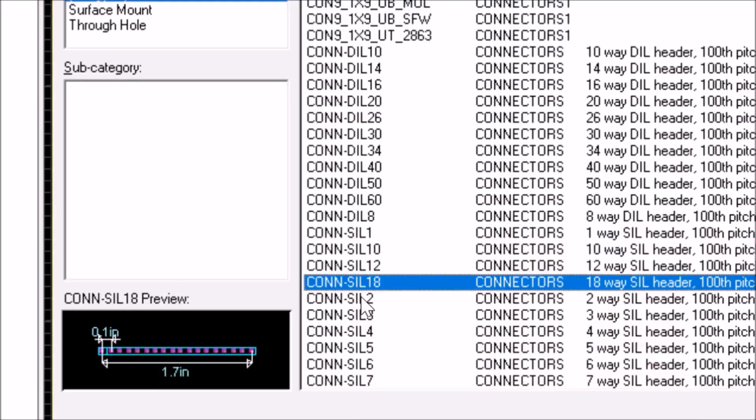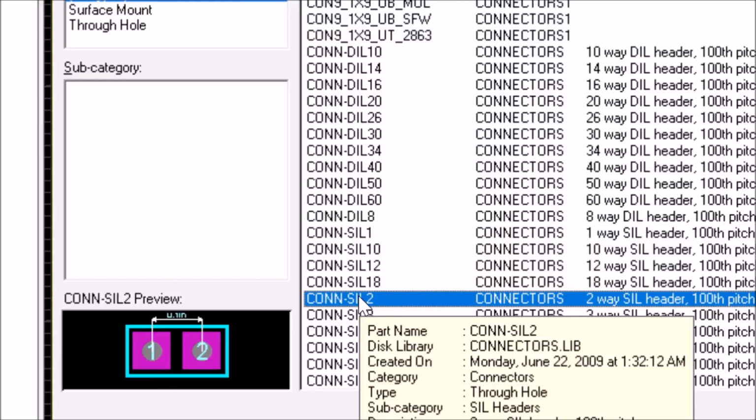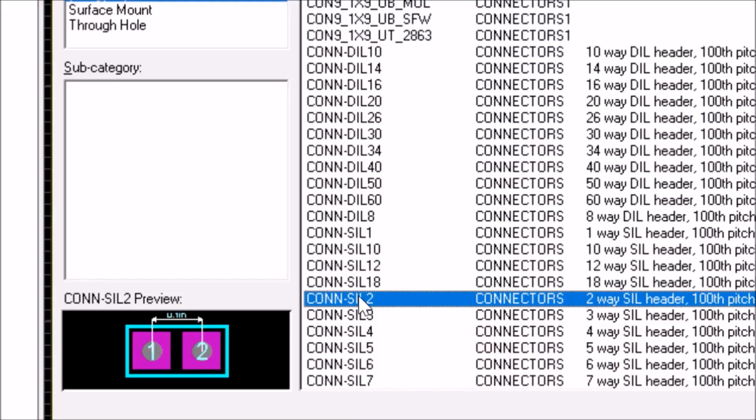Why am I clicking on 2? Because I have 2 inputs, and I'm not going to put the AC on my PCB. On my PCB board, I don't want to connect AC directly, because the PCB is meant to be just a low voltage circuit board. And in case you connect your AC there, you might have an electrical shock. So all I need is the output from the transformer, because that is already stepped down, and that we have no shock on me.